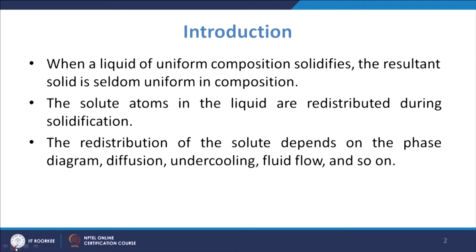So the solute atoms in the liquid are redistributed during solidification, and this redistribution of the solute depends upon the phase diagram, diffusion, undercooling, fluid flow, and so on. These are the factors which define how the solute will be redistributed.